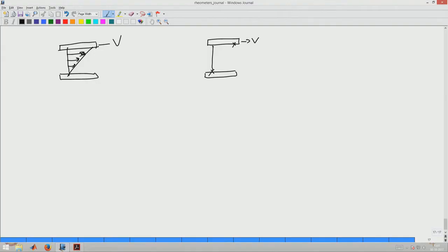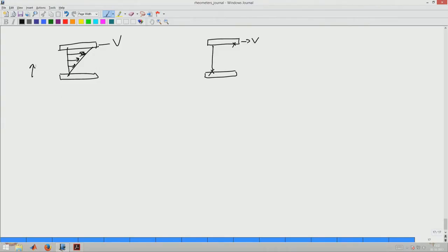So, what do we mean by instabilities? No, so secondary flows is one aspect. So, in that case what happens is we will still have one dimensional flow. Okay. So, if we have secondary flows, then there is flow in the other two directions. For example, we are generally mentioning that there is only Vx and we say that Vy and Vz are 0, right. That is the assumption that we are making. So, secondary flows, whenever we say, that means that Vy and Vz are also there. So, let us still assume that we are able to do flow where Vy and Vz are still predominantly 0.